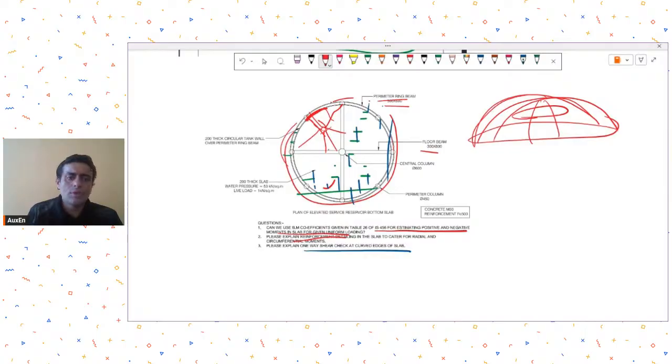So first you need to estimate the shear value, for which you don't have a really good way of doing it. If you have estimated the shear, then the shear check remains the same. You find out the Vu, it has to be less than Vc. That check remains the same. Maybe over 1 meter curved length, you can do this check. The problem will be to estimate how much shear you will get on those curved edges.